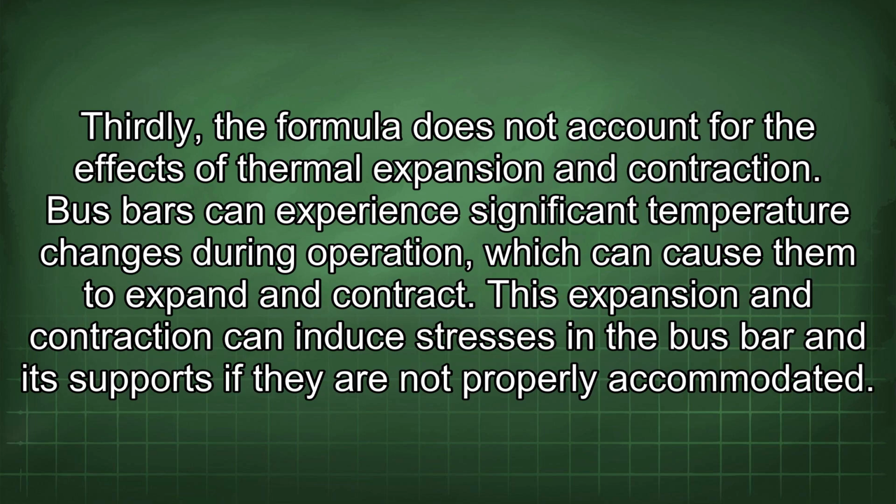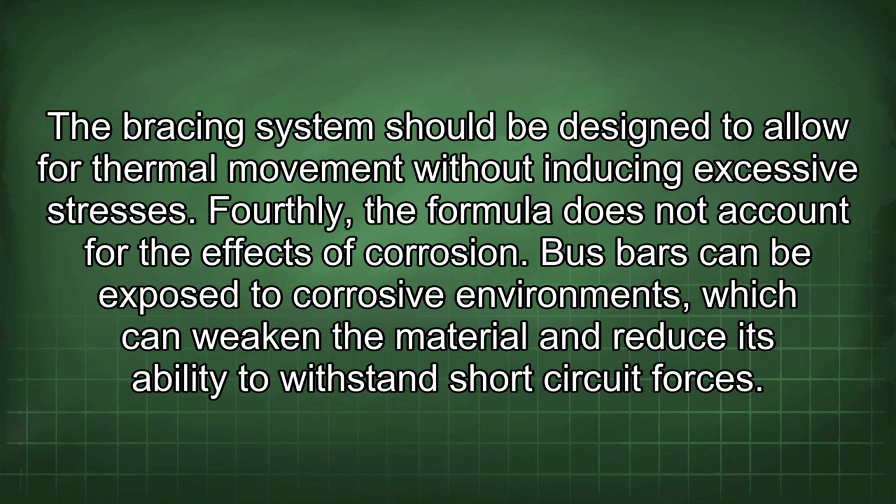Thirdly, the formula does not account for the effects of thermal expansion and contraction. Busbars can experience significant temperature changes during operation, which can cause them to expand and contract. This expansion and contraction can induce stresses in the busbar and its supports if they are not properly accommodated. The bracing system should be designed to allow for thermal movement without inducing excessive stresses.